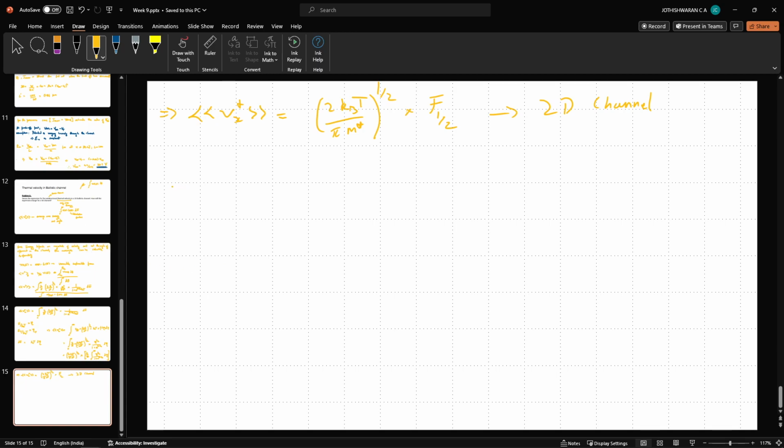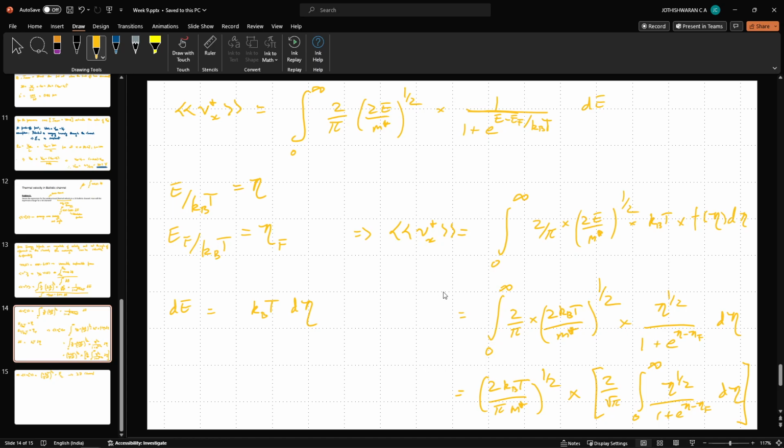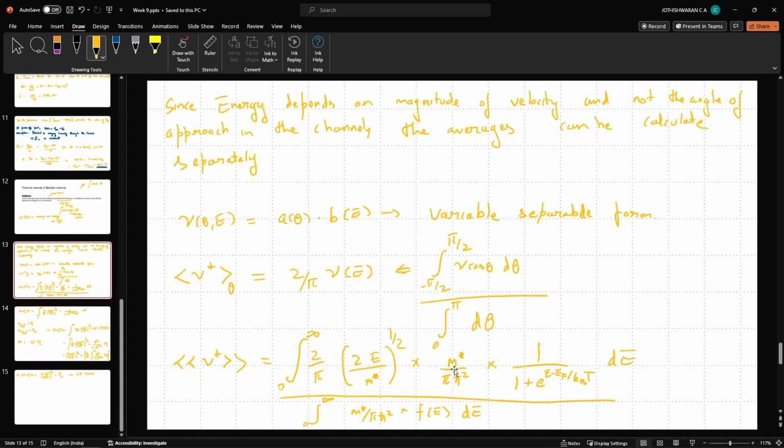What I will tell you is, for a 3D channel, one thing that will change is this. This constant factor that I mentioned will no longer be the case, because density of states will now depend on the energy values. Because of that, we will have an e to the power half term over here and an e to the power half term already over here. Every other constant will still get cancelled out.